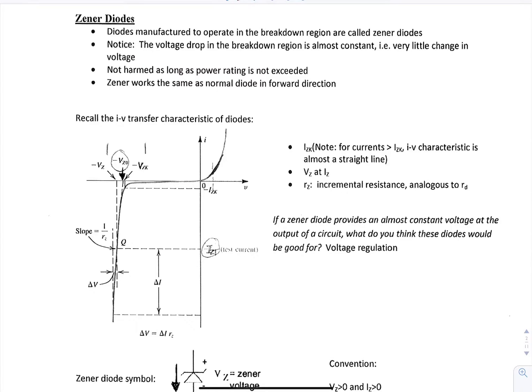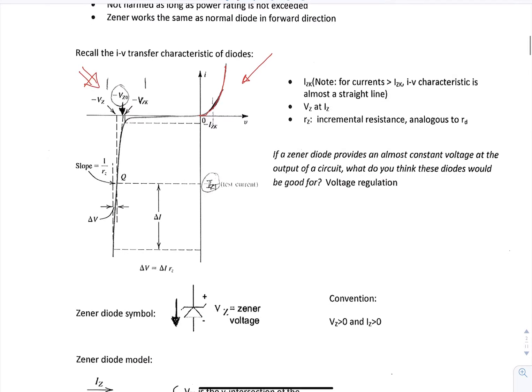And so the Zener Diode's graph looks like this, where in the forward direction, it has the same curve that we have seen for a normal diode, but in the backwards direction, it actually gives you this nice curve here where once you reach this minus VZ0, then it will turn on and let current flow in the opposite direction. So this is very useful for a voltage regulator.